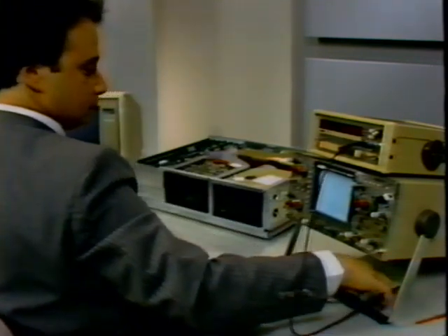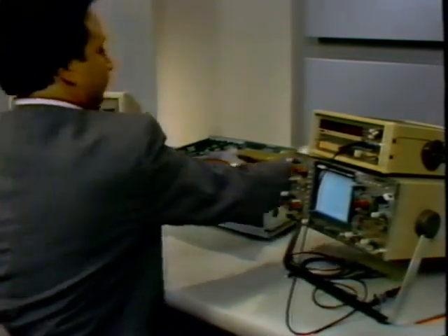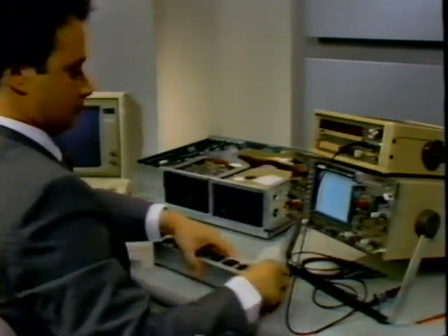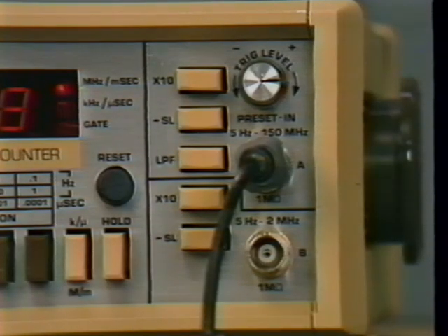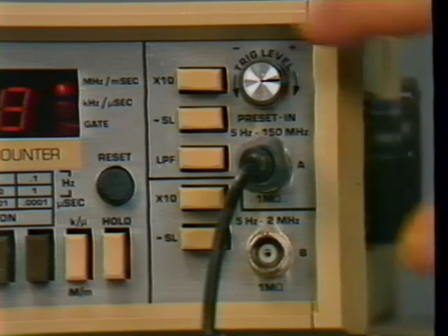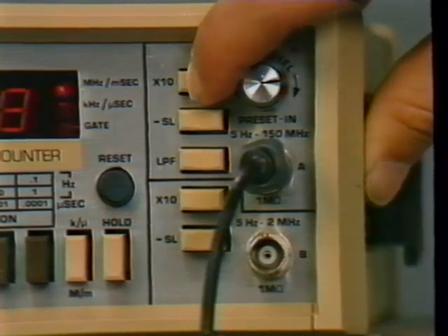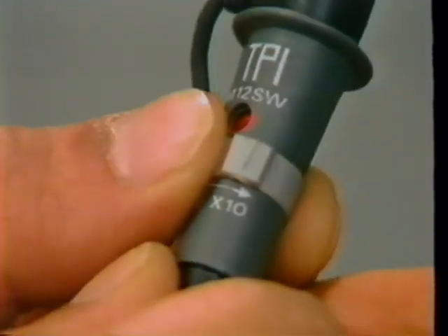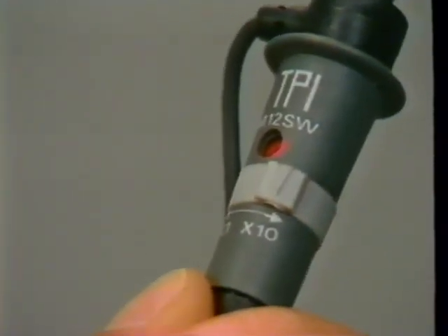We can use a frequency counter to check the AC line frequency if necessary. Since this is a very high AC voltage, we will set the counter up somewhat differently. In this situation, set both the probe and the counter switch to ×10. This 100-fold attenuation is necessary to prevent damage to the counter. Do not ground the counter when measuring the AC line. It would be possible to use unmatched ground points and destroy the meter.